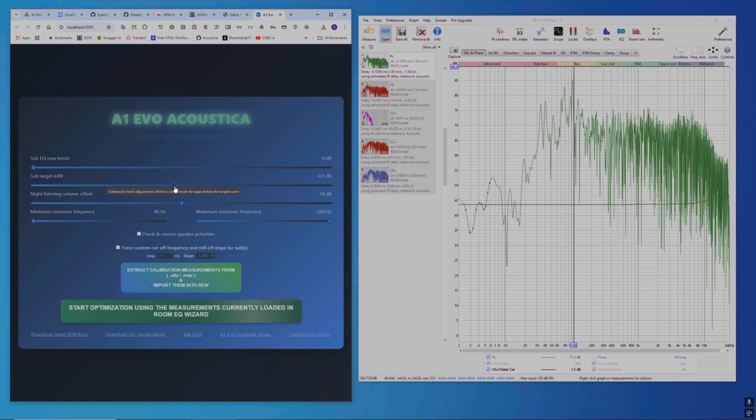like that. You can also use this if you took subwoofer measurements off by 10 dB, because with manual measurements it's quite common. People forget to use LFE minus 10. LFE measurements by default are 10 dB louder than speaker measurements. Dolby has 10 dB louder embedded in the LFE channel. So if you forgot to measure your subwoofers 10 dB lower, then you can use the 10 dB here as the offset. That's the only reason there is 10 dB here, otherwise it's really too excessive to use 10 dB.